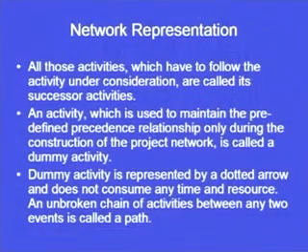Then in network representation, an activity which is used to maintain the predefined precedence relationship only during the construction of the project network is called a dummy activity. The concept of dummy activity has been introduced in the construction of the project network representation. Already in the course of this lecture, I have told you that there are certain activities which do not require any time and resources. These are the activities which are called dummy activities.